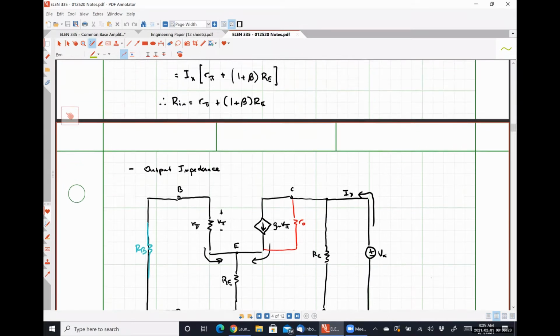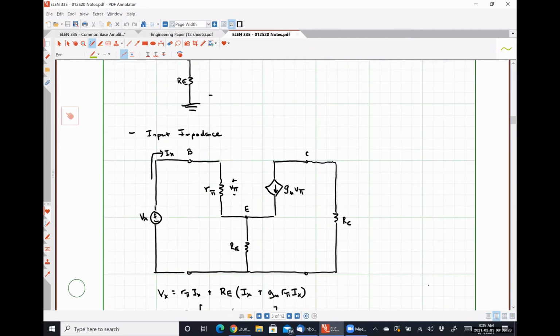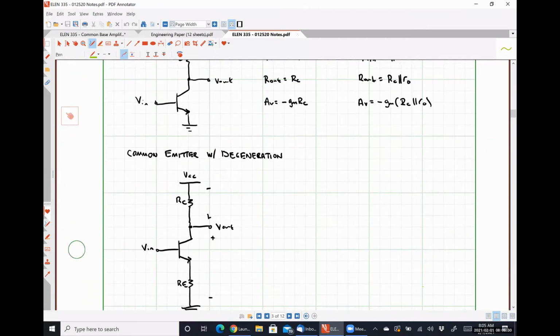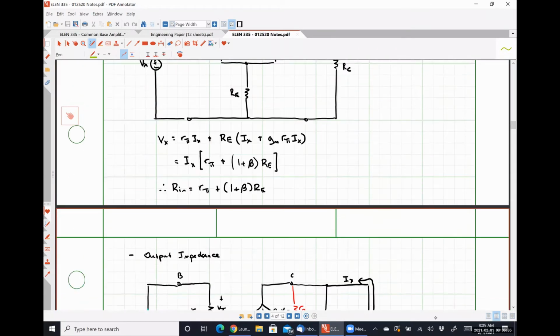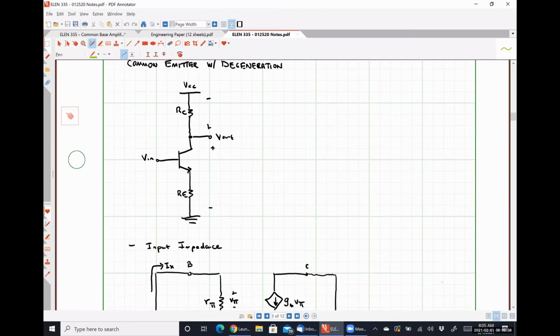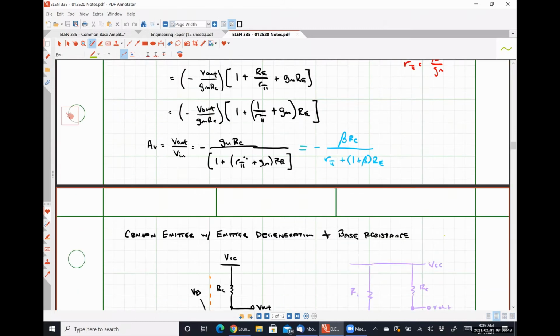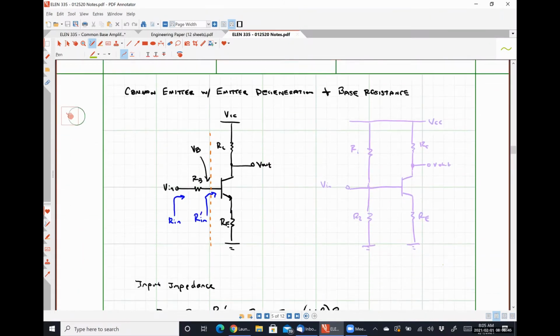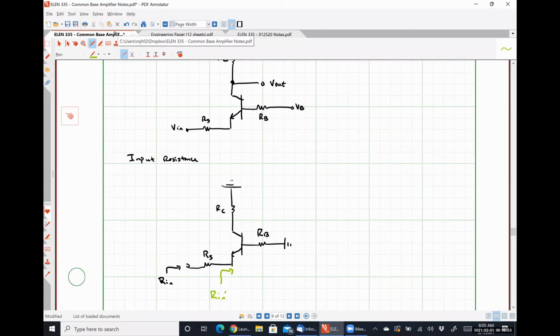So what I believe I've just opened up is my common emitter amplifier configurations. Yeah. I want my common emitter with a base resistance. Sorry, let me find that real quick. All right, so I would argue that looking in through this specific terminal where I've labeled it as green, the collector terminal, we're kind of looking past that resistance RS.